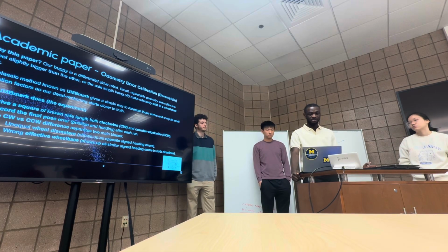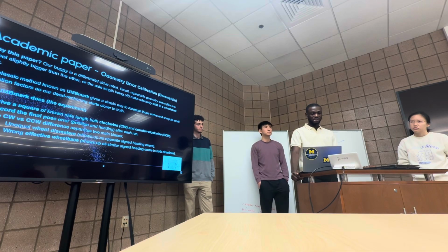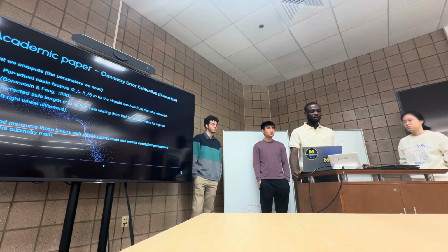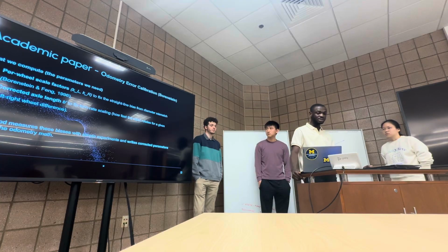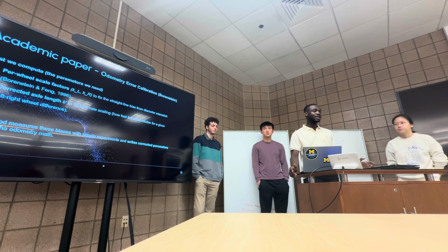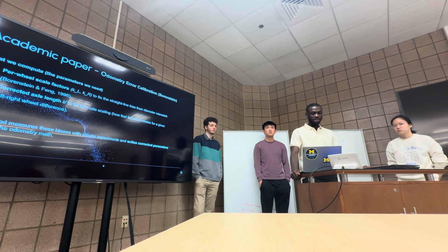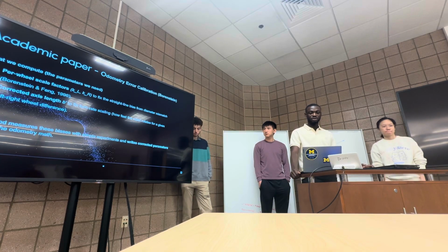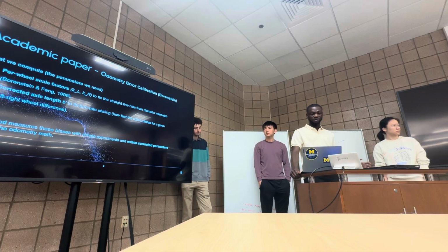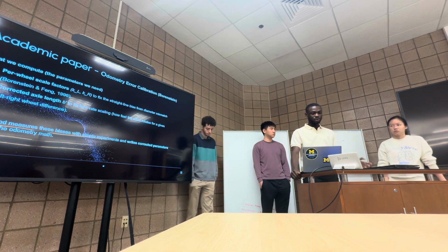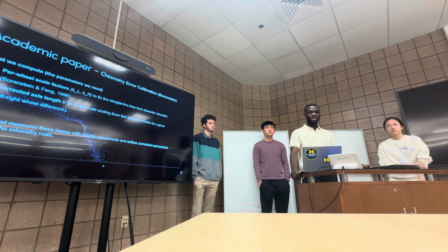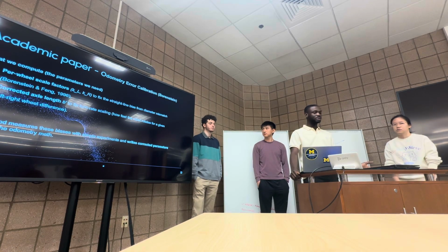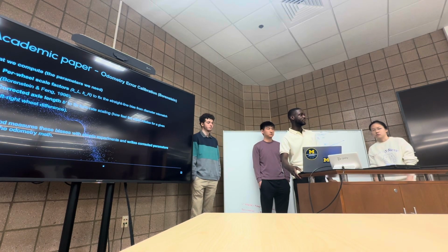The clockwise and anti-clockwise difference separates two main biases, which are the unequal wheel diameters and the uncertainty in the effective wheelbase. The parameters we need to compute are per-wheel scale factors to fix the straight-line bias from the diameter mismatch, and a corrected axle length to fix the turning scale, which is how fast the robot rotates for a given left and right turn. We'll measure these biases with a simple experiment and then write the corrected parameters back into the odometry class. My colleague will now explain the method in detail.